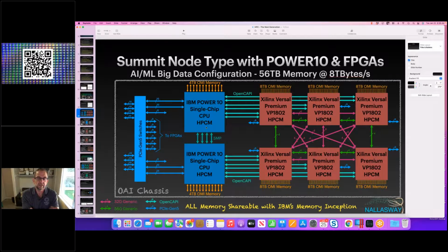So I think to have one of these FPGAs act as the BMC, I think that's the Libre BMC concept. That would be good, and it can do all of the stuff that it would do on the host side. It can power all these chips on and off, talk to the VRMs and collect the inventory. But then I'm just looking for that connection from that BMC on this module back to wherever it's going that is actually the manager. Yeah. Ideally, I'd like this to be usable as a standalone box.